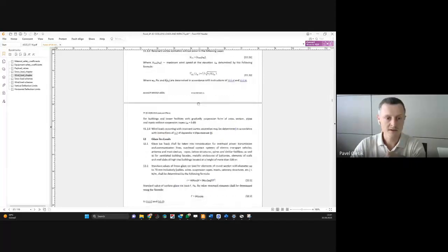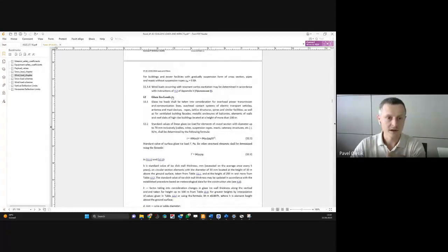Okay, I'm not covering this. Ice loads also usually we don't calculate. We calculate it if we have, for example, some electrical supports with hollow structures. So for structures which are not affected by wind too much, where self-weight is small, and we have a big covering area, this kind of structures must be calculated for ice load. For usual structures like square, we don't calculate.